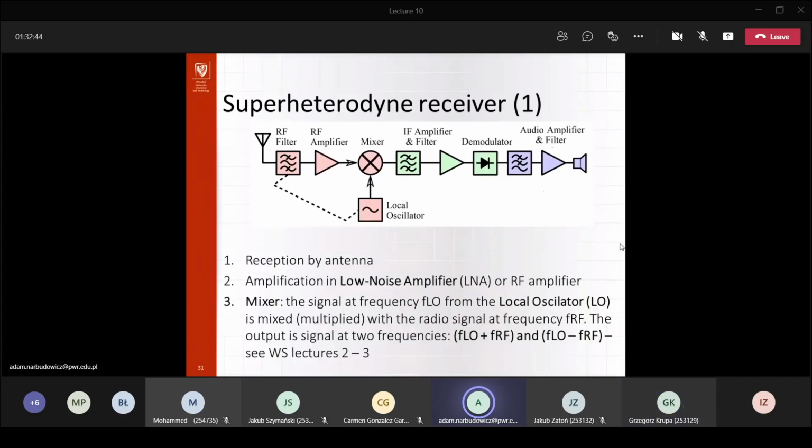The rule is, as I mentioned, that if you're using any two signals, the difference between them and the multiplication of that would generate all the intermodulation products. But the third one would be the closest one.